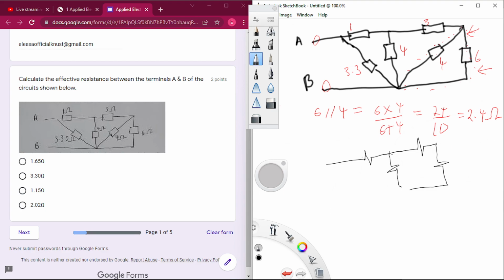So considering 2.4, we realize that this is not a node. But in our drawing, we have brought it down just so we can have that closed circuit. It could have been curved. So realize that over here, this is one branch. And since we have two resistors in the same branch, 3 and then 2.4 are in series. That's 3 plus 2.4, which is 5.4 ohm.